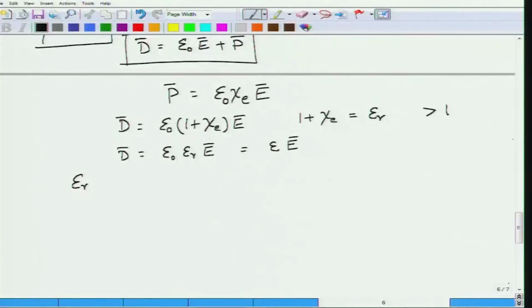Okay. So this directional dependence can also be considered macroscopically and attributed to the susceptibility chi e or the permittivity epsilon r, or its shortened version epsilon. So we say that epsilon, which varies with respect to space or the spatial coordinates, is an inhomogeneous dielectric. If epsilon is a function of the angle of the applied electric field, that is the direction of the applied electric field, then such materials are called anisotropic materials.